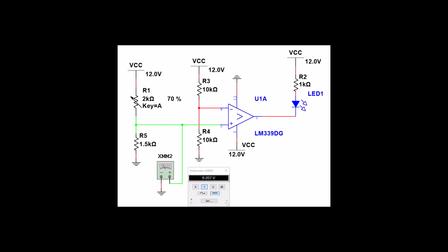And there at 70% our light turns off. So we keep going down, same thing. Alright, it's getting dark again, so let's raise the resistance of our photosensor, and it's dark at 75%.